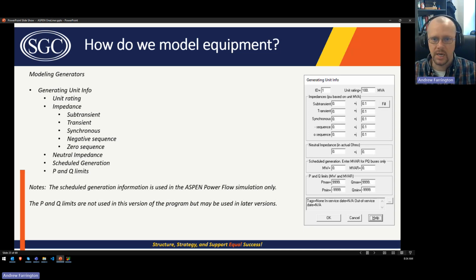But if you've got a time overcurrent relay that is looking out into the system and it's got the generator behind it, but it's operating, say, in 2 seconds or a second and a half or whatever, the amount of fault current put out by the generator is substantially lower in that synchronous range, in that 1 to 2 or 3 plus second time frame.